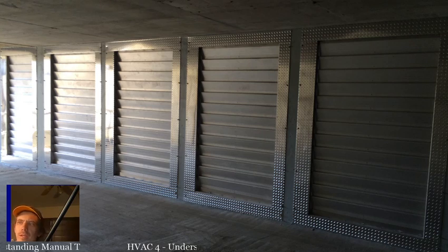But you can have non-vented infrared heaters, right? If you have a non-vented infrared heater, or any other non-vented appliance, you want to make sure that it is in an area that is well ventilated, right? You don't put a non-vented appliance in a very non-ventilated room, so you're not going to stick a non-vented heater in a small bathroom or something, right? Because there's not enough ventilation in the room to deal with the products of combustion. Just because it's labeled to not require a vent doesn't mean that it's not going to have products of combustion that need to be vented.